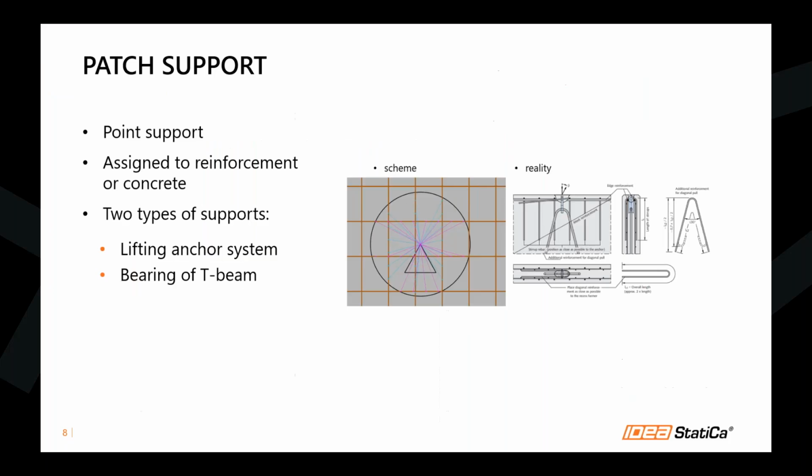So for our case, we will use a so-called patch support. This patch support is actually a point support with a specific area through which the reaction is transferred to the model.